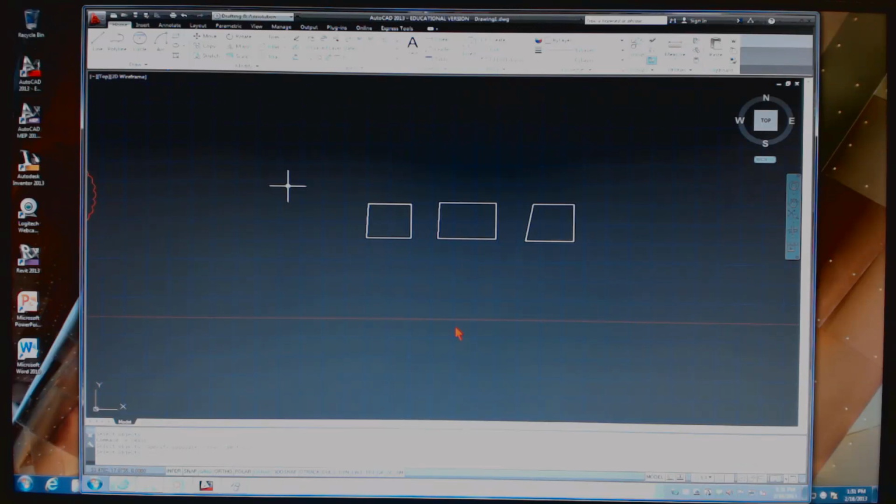So I'm going to show over real quick how to set up multi-view drawings. What you're going to have to use is called a miter line to create them. You get all the dimensions, but this is what you're going to have to learn real quick. When you draw a multi-view drawing, you can't finish one view before you start the other.